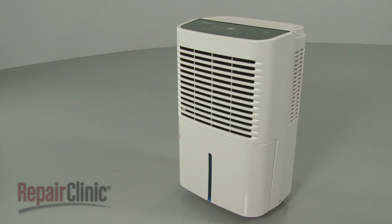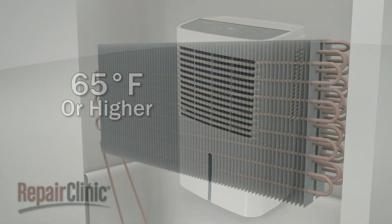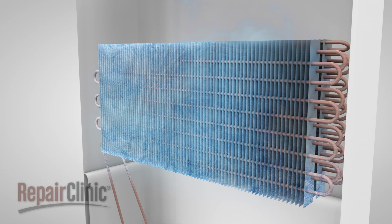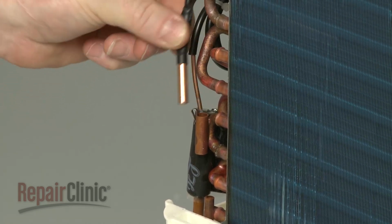Most standard dehumidifier models require the room temperature to remain above 65 degrees Fahrenheit for the appliance to work properly, as lower temperatures can cause the evaporator coils to frost over. If the temperature in your home regularly drops below 65 degrees, you will need to obtain a model that is specifically designated for lower temperature operation.